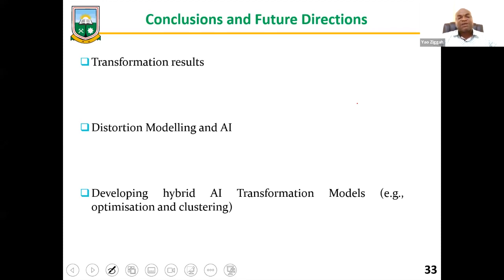Normally, because the conventional techniques are handicapped, when you perform the transformation, let's say Bursa-Wolf, you need to move a step further by doing the grid-based transformation to improve the result.